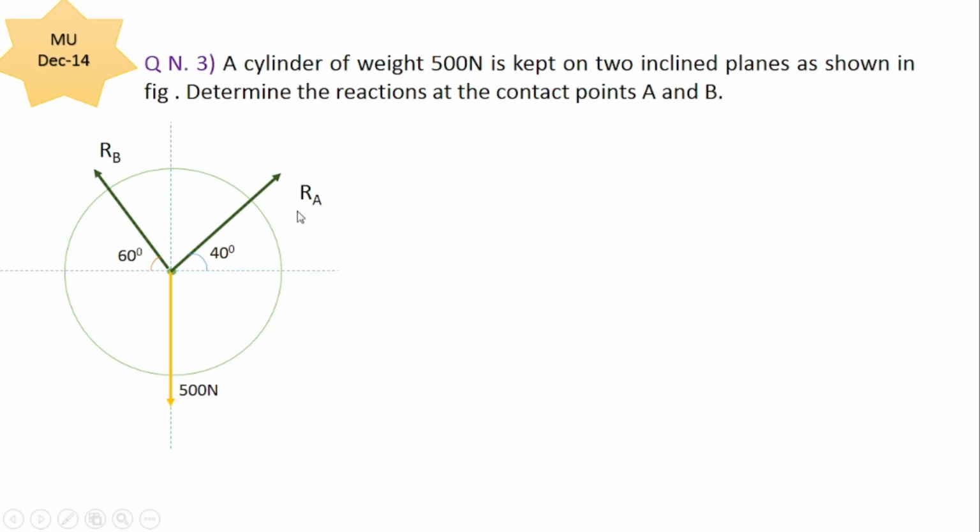Now we can solve this numerical by applying Lami's theorem. Why? Because the system is in equilibrium, it consists of three concurrent forces, and they are pointed in the same direction. So it satisfies all the conditions of Lami's theorem. So we'll start with applying Lami's theorem.